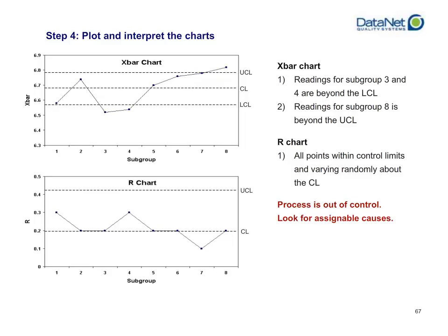In each one of those 3 cases where you fell outside of control, you should have tried to investigate had you been plotting this in real time. And you would have been able to plot this in real time had you had enough data historically to actually go in and begin plotting this. This is where WinSPC comes into play. You would have been able to catch these out of controls immediately and begin to investigate and determine if it was in fact a true positive or a false positive.